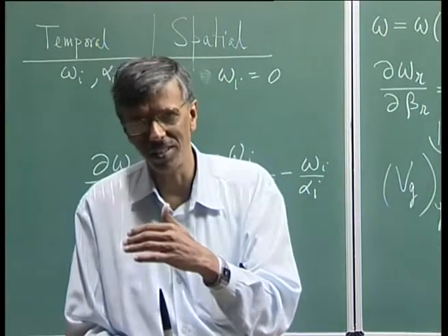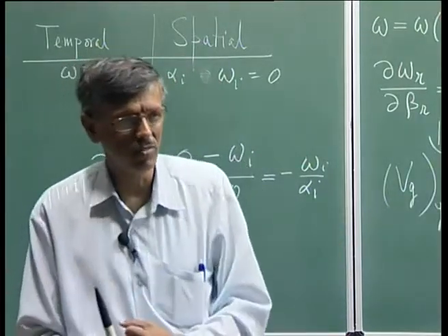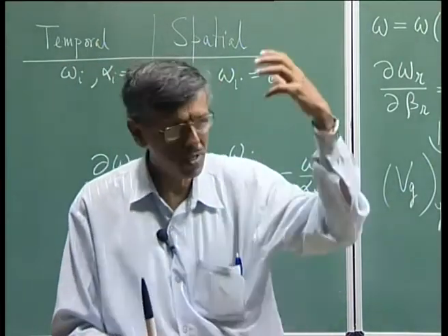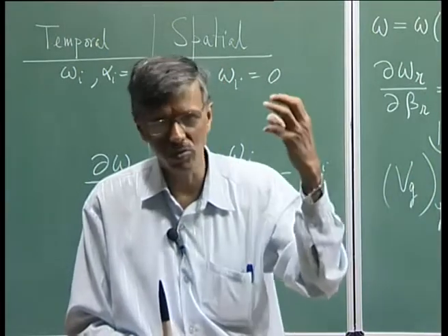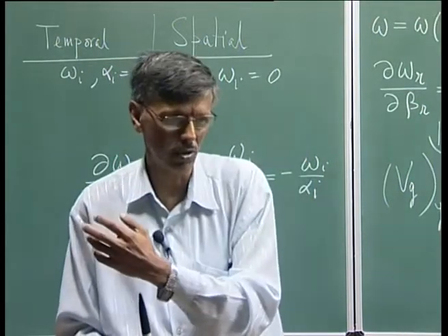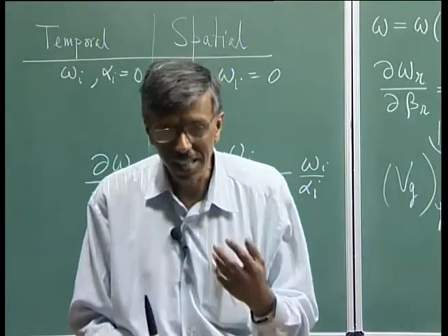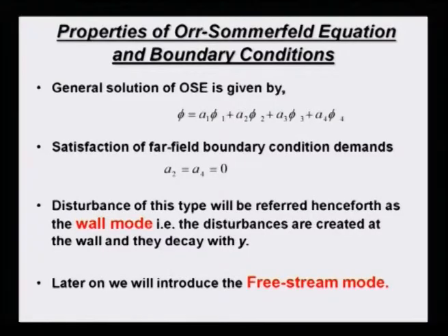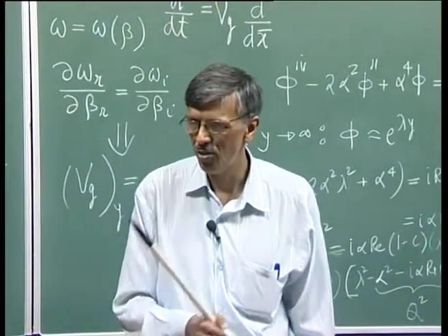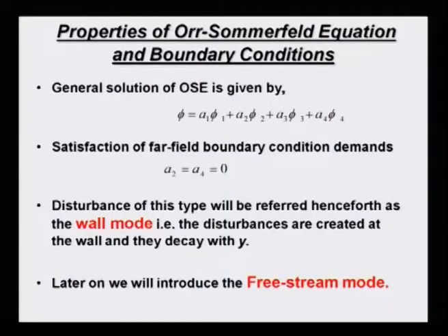Those vortices go downstream, because that is the mean convection direction. When it comes over the stator, these vortices are not immediately ingested inside the boundary layer, but they remain outside the boundary layer, and those vortices originating from the stator, as they convect over the rotor, they create instability. That is a scenario what you would call the free stream mode. Okay. So, there the disturbance resides in the free stream, and you want to find out what it does inside. We will have a lot of discussion on this as we go along.